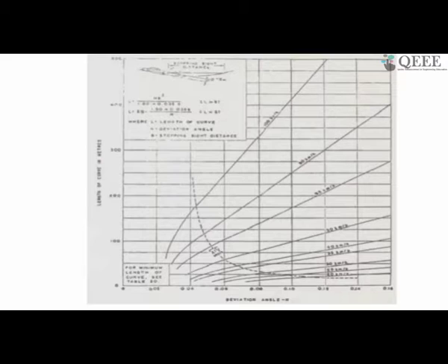Now in both cases, basically we are doing this because there is a change in gradient. Now you can flatten out the gradient. What is going to happen? Your earthwork is going to increase and your construction cost is going to increase. So I'll come to those things, like flatter gradient and what is the effect, when we actually see the next few slides.